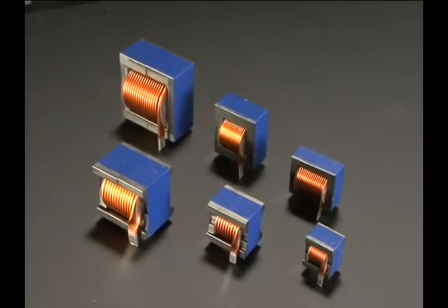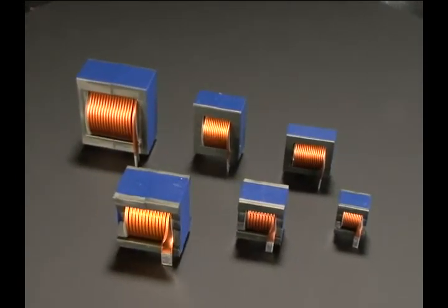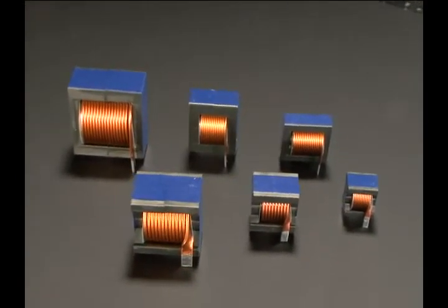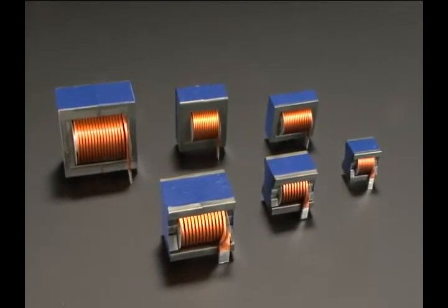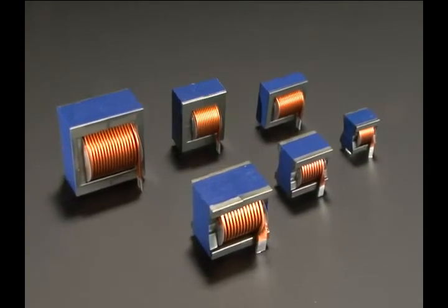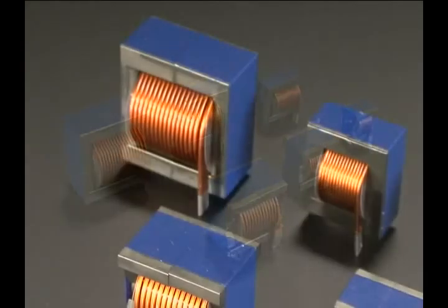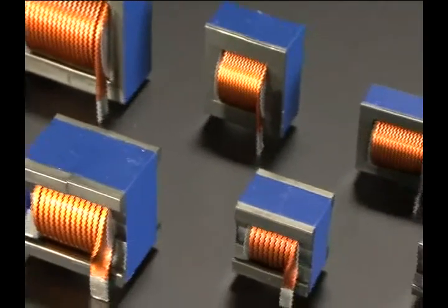Compared to resistors and capacitors, inductors are less susceptible to damage. When they are damaged, it is often difficult to detect from external appearance alone. Insulation film applied to the coil will deteriorate in environments with high ambient temperatures. In the worst case, the coil short-circuits and is no longer capable of functioning as an inductor.